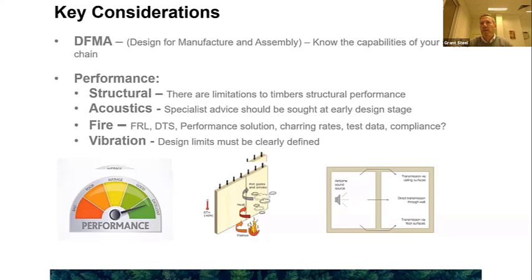Last item on this slide is vibration. Timber is a relatively lightweight form of construction. It requires a little bit more consideration when it comes to the vibration design. Stiffer floors typically perform better. More mass typically performs better. Sometimes it's necessary to include dampers to add more mass to the floor.